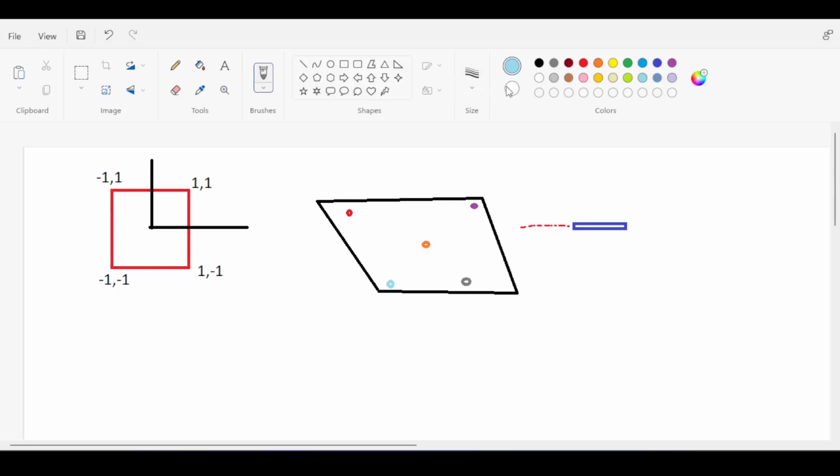Now, those points do have, of course, values, because you remember those maps are actually color coded. Please notice that it's much easier for us to calculate everything related to stiffness for this simple element because of the convenience of its coordinates and the convenience of its shape functions. This is something really technical. I don't want to dive into finite element right now, but I want to give you enough knowledge to understand that the element on the left is much easier than the element on the right in terms of calculating stiffness. As a matter of fact, the element on the right is a nightmare.